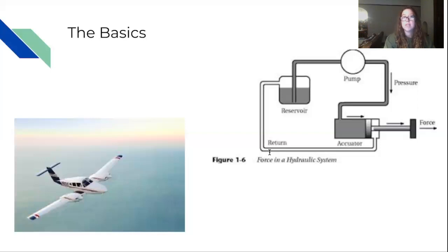Different aircraft may use either a pressurized or a non-pressurized reservoir. In smaller airplanes, the non-pressurized reservoir is going to be more common. The pump is another important one of those six basic parts of each hydraulic system. This will take power from either the engine or an electric source and work to move that hydraulic fluid and apply pressure to different parts of the system as directed.